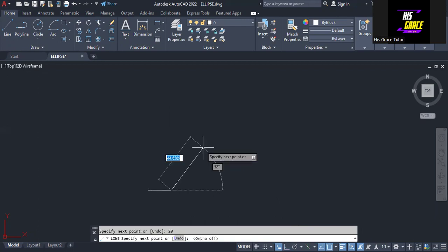Okay, so the side that we are going to draw also has a length of 20. This is a regular pentagon. So the next thing that we are going to do is enter 20 for the length. Then you press the tab key, and for us to enter the angle at which this line will be to the horizontal, that angle is 72 degrees because the exterior angle of a pentagon is 72 degrees. So we press the enter key.